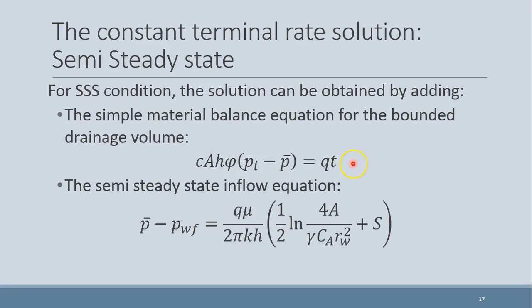This is the underground withdrawal, and that would be equal to the volume produced in time t. This c is to account for the expansion, the compressibility of the liquid, because in reservoir conditions the reservoir fluid will be more compressed because the pressure will be higher, and at the surface the fluid will expand a little because of lower pressure.